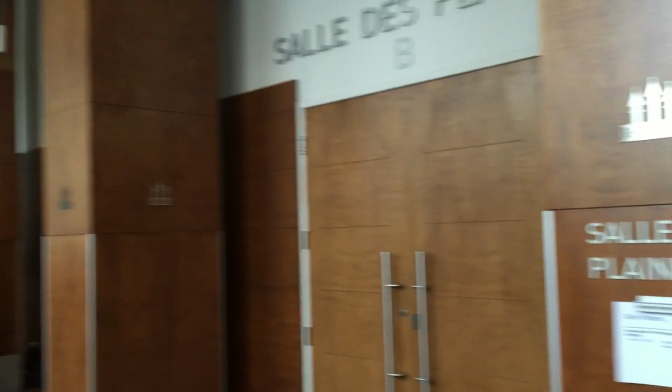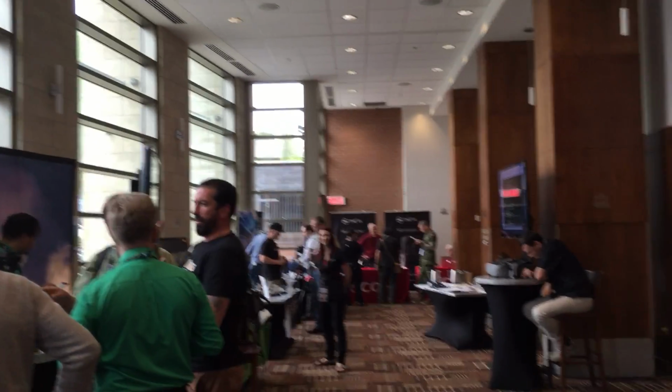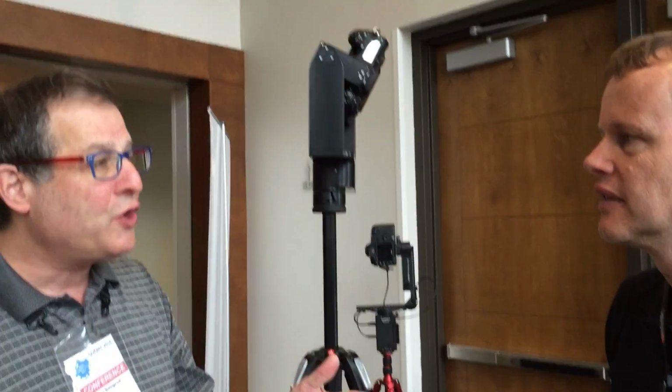And so, for a space this size, for example, let's say we didn't have floor plans for this lobby. If you want to have no occlusions, I would say create at least 10 stations. An occlusion would be, if I take this and this, I'm going to have maybe some spot where I'm missing data, mostly related to tables. So if I really wanted to capture all the data around the spot that the camera can't see, I have to keep moving the camera to find those places in order to capture the images that will be used to create this.